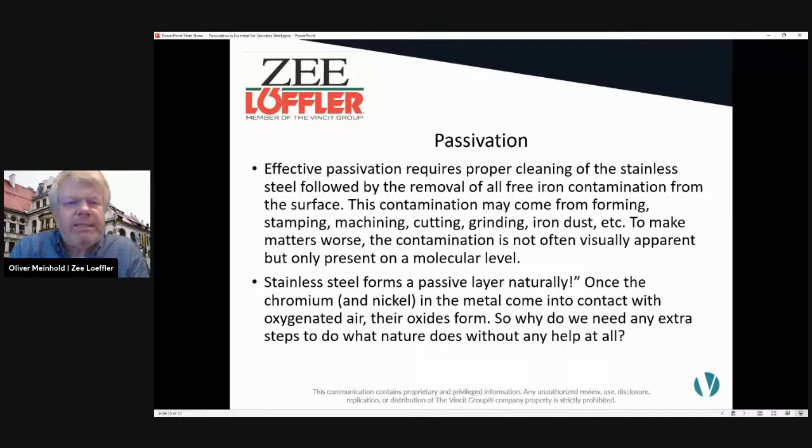Before you do the passivation, like I said, cleaning is very important. Just the grease of your skin, after cleaning your tank, when you have removed all the oil and other impurities and you just touch the surface with your hand, this little bit of grease from your skin is already enough to protect the stainless steel. Then when you run a passivation procedure and rinse everything out later on, you can actually see your handprint. So this is a very important thing: the surface of the stainless needs to be absolutely free, accessible to oxidation, either from a chemical or from the oxygen in the air.